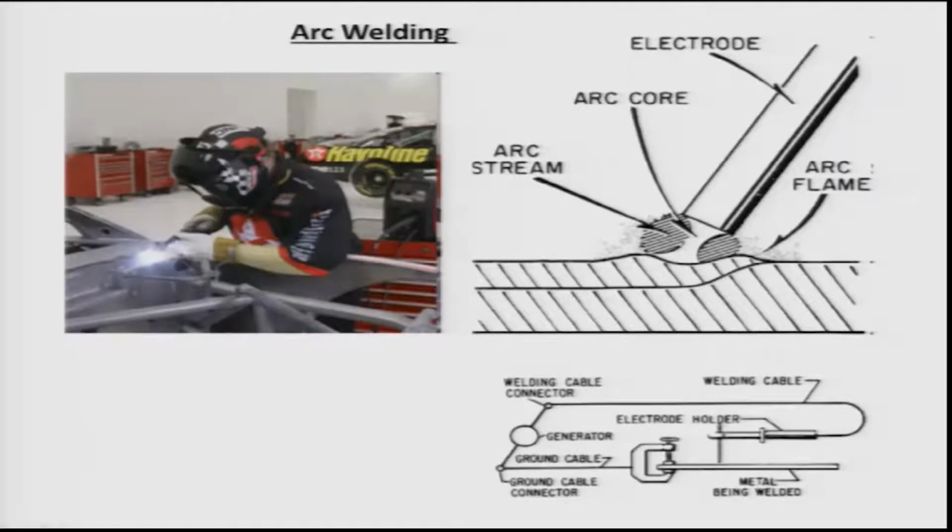Well, not only that, there are welding techniques in which solidification takes place every time a weld is made. As you see here, this is arc welding, in which an electrical arc is used to join two pieces of metal. Basically it's nothing but a tungsten electrode. Normally it can be used to generate only the heat, and sometimes we also use a feeding electrode which will melt and allow us to join the two metals.